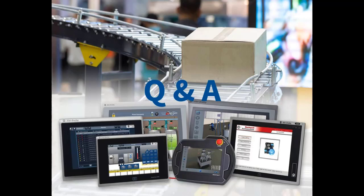Thank you. Can the PanelView 5000 terminals be used with the existing SLC 500 controllers? Derek? No, your SLC 500 will not talk to the PanelView 5000. They are compatible with the CompactLogix and ControlLogix controllers. If you are still using an SLC 500, we recommend finding a migration path to something newer.